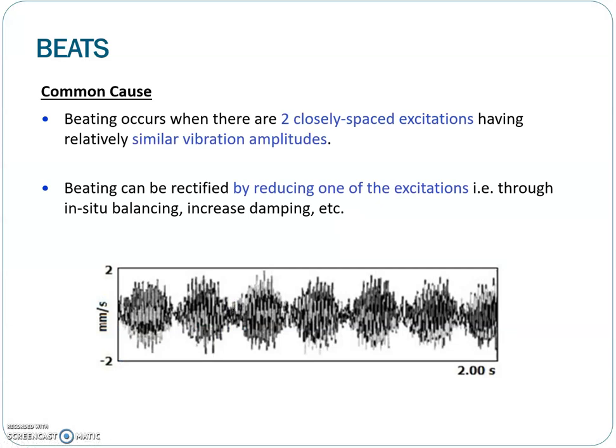The next machinery fault that is associated to non-sync vibration is beating. Beating can occur at any frequency when there are two closely spaced excitations having relatively similar vibration amplitude come together. Beating can be rectified by reducing or removing one of the excitations.